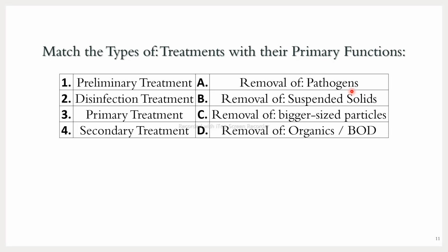And another way is UV treatment, which is generally used in industrial waters. For example, if the water is used inside the reactor for making a product, there may be biofilms present inside the pipe if there is stagnancy. So before and after any stagnant region of the pipe, UV lamps are generally stationed. UV lamps destroy the bacterial cell wall with their high radiation, and also modify the genetic material of the bacteria, and in this way it disinfects or removes the pathogen from the water.